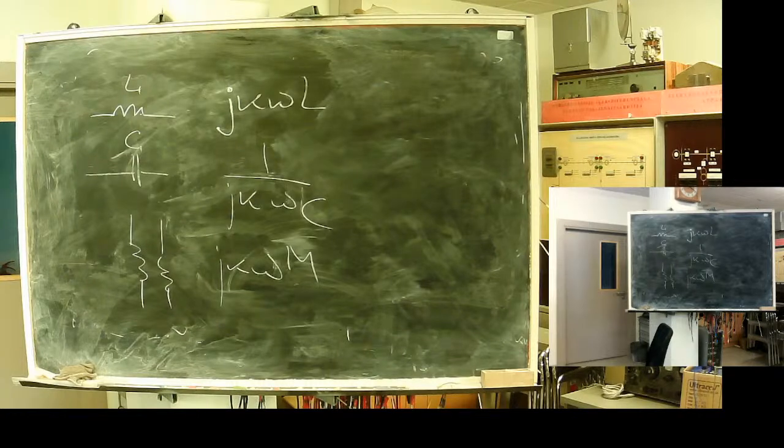The first branch was 222 ohms. The second branch 8 millihenries. The third branch 94.7 microfarads. You see, 94.7. Capacitance, right? Yes, it's a capacitance. 1 divided by jK omega C. Then 79.4 ohms, 6.8 millihenries. The matrix is recalculated for each harmonic.